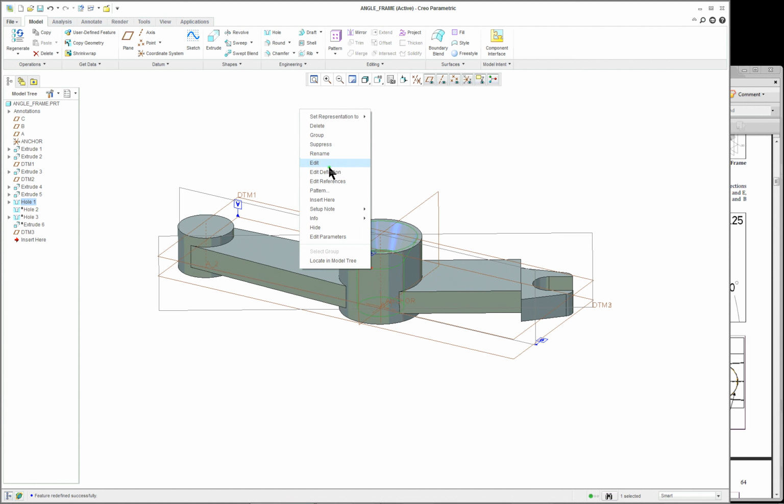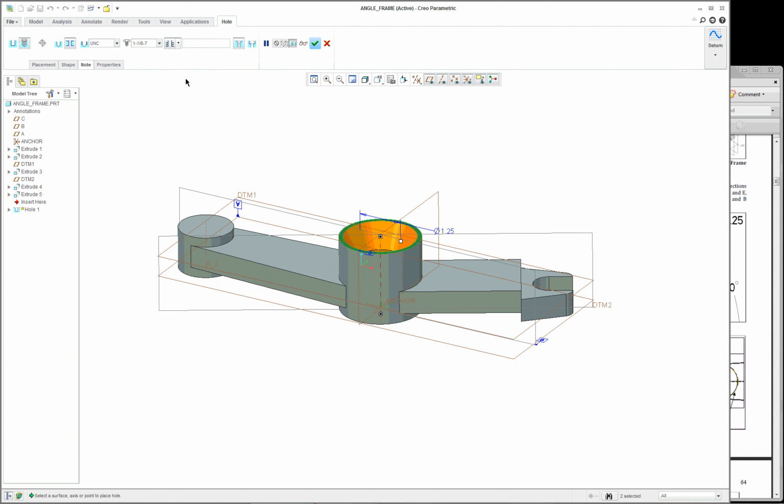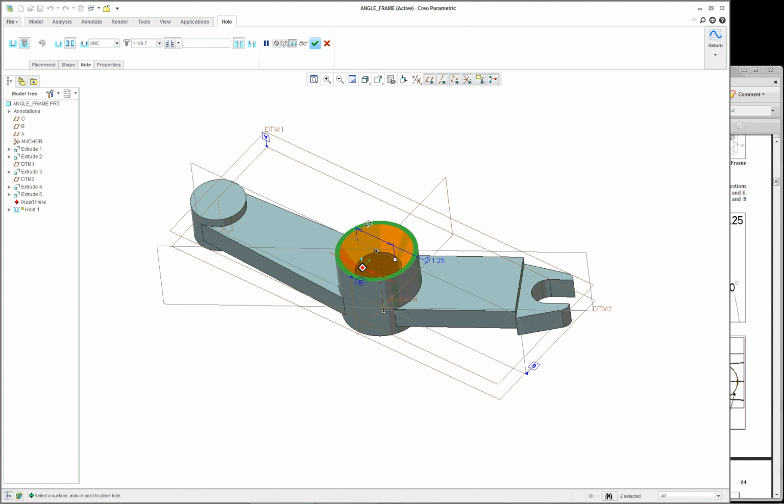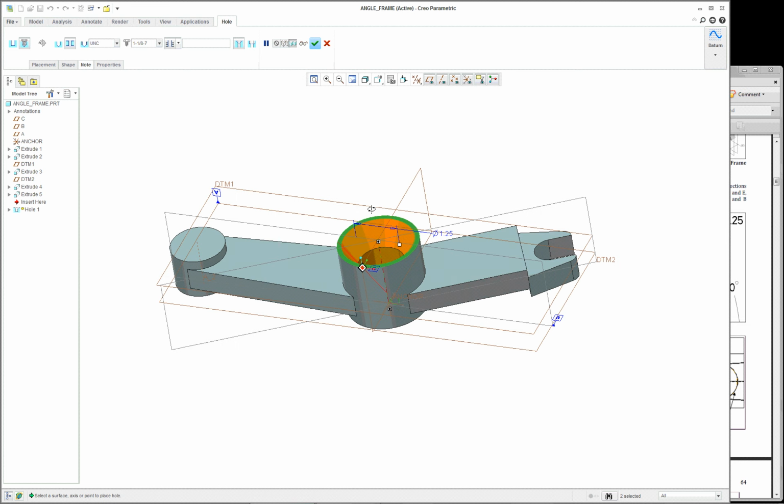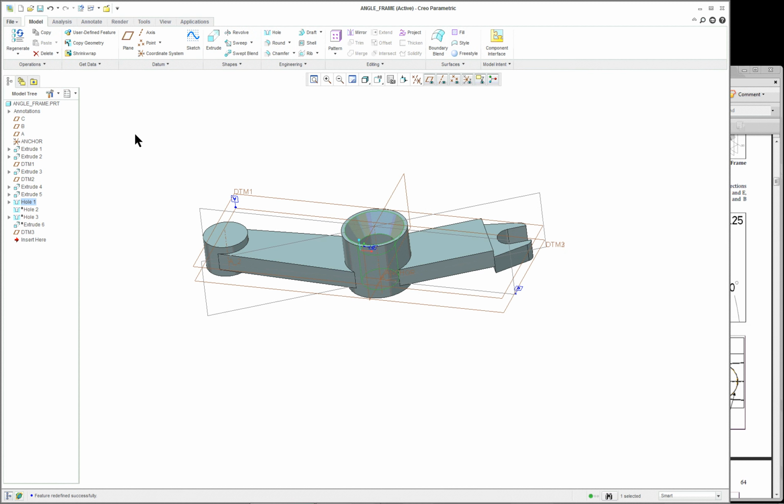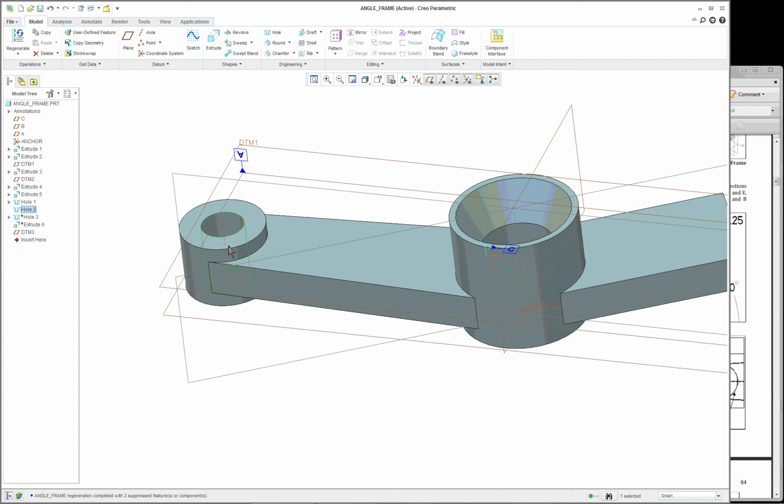Let's look at it one more time. You can do this a variety of ways. You could have done a revolved cut. You could have done a hole with a sketched hole, or you can just put it in and use the chamfer here. Countersink. Next hole is on the other side over here, and you should be able to do that by now.